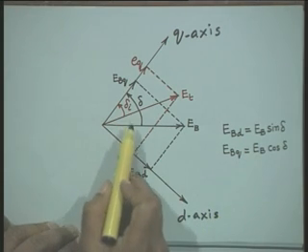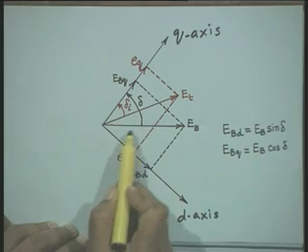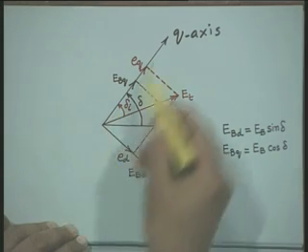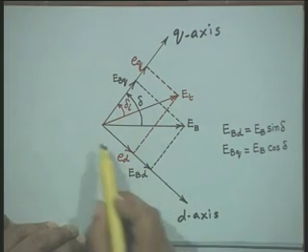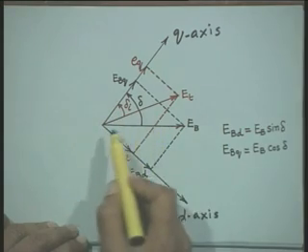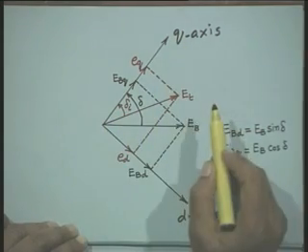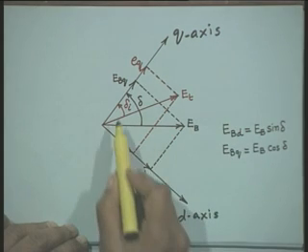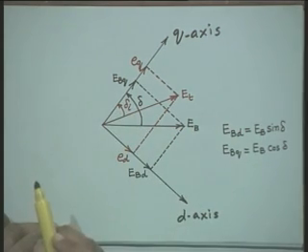Then the definition of this power angle delta is the angle by which q axis leads E B. The delta is positive when q axis leads the infinite bus voltage by an angle delta, while the internal angle is the angle by which q axis leads terminal voltage. The delta I is the internal angle and delta is the total power angle.